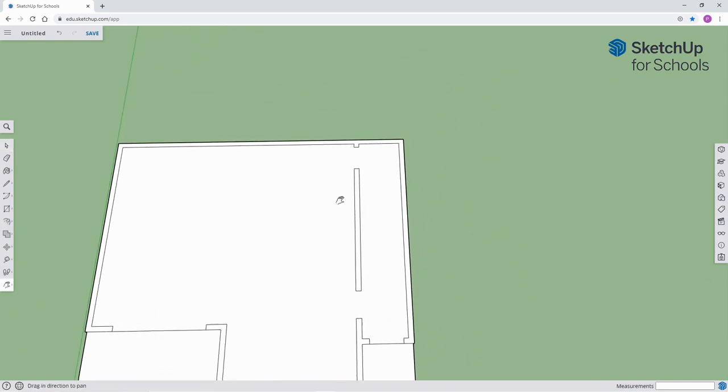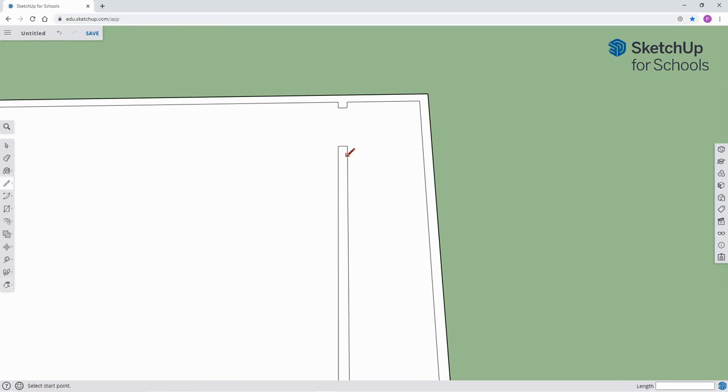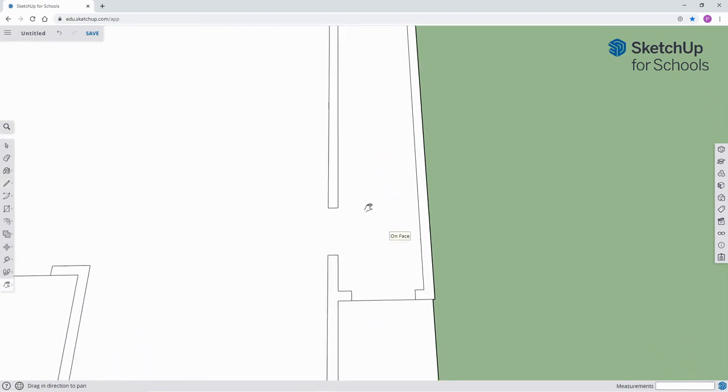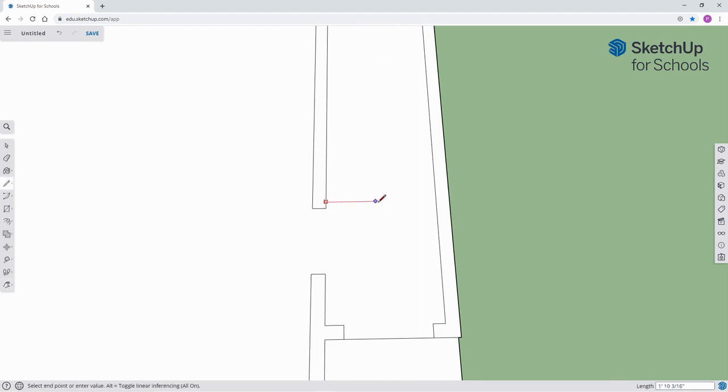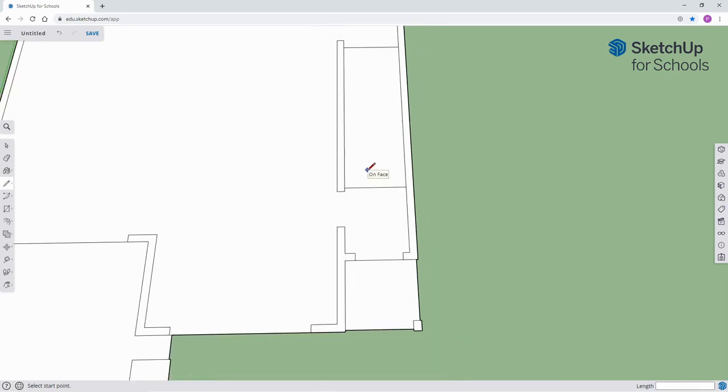All right. Now, I'm going to enclose the area for the staircase. Here, I will click on this edge and I will divide it 15 times. I'm just testing now to see if the division took place. And I can see that it has. I will now use the line tool and the endpoints to create what will become my steps.